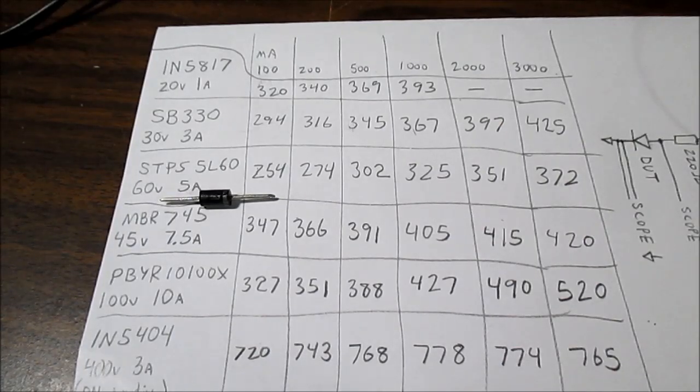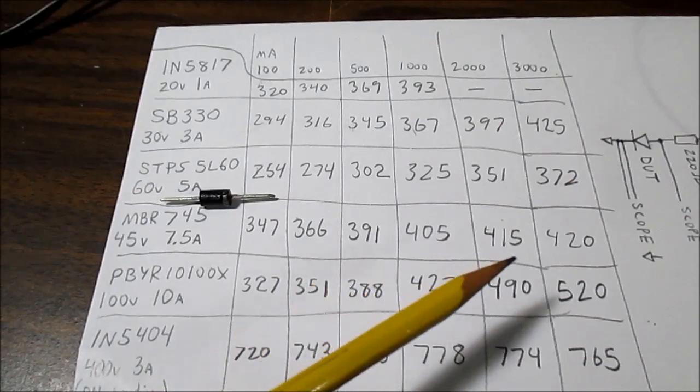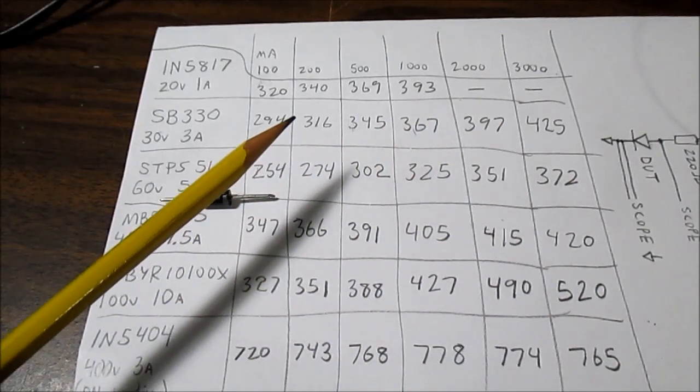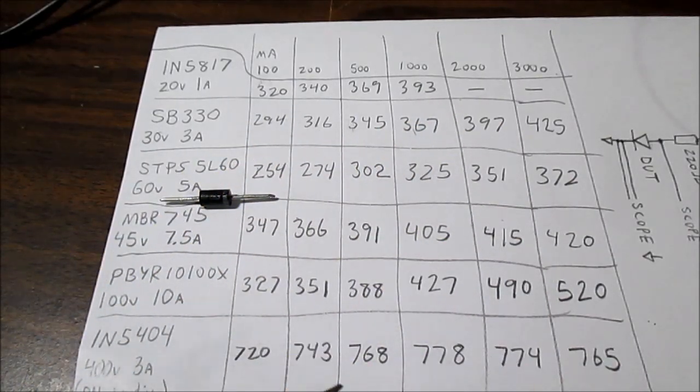Now, in recent years, they've come up with higher voltage Schottky diodes. I guess they're based on silicon carbide, and they can operate up above 1,000 volts. However, their forward voltage drop is not as good as these lower voltage ones, but they still might be better than a standard silicon diode. In fact, they are pretty close actually. It's mainly the fast switching speed benefits you get from those.